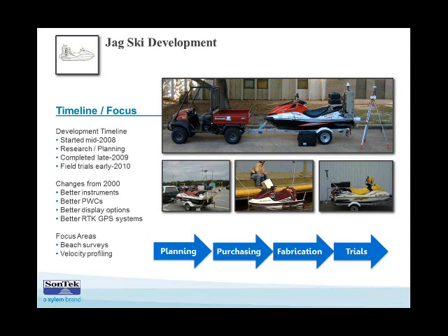And with the few minutes remaining here, I wanted to step you through what I would have to do and what I have done to perform a survey of the flood shoal here at Little Lagoon, and just reduced it down to 10 steps with corresponding images on the right. So the first thing I did was use the native mapping images that HydroSurveyor has in its software to cache a local image of my study area. That way, when I don't have internet connectivity on the water, I can still have my background image if I want it.